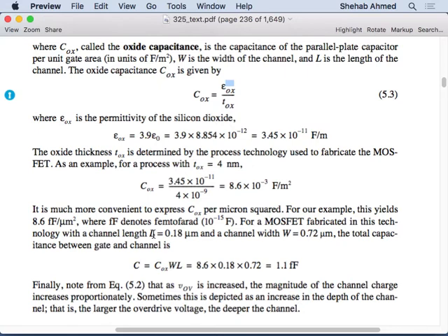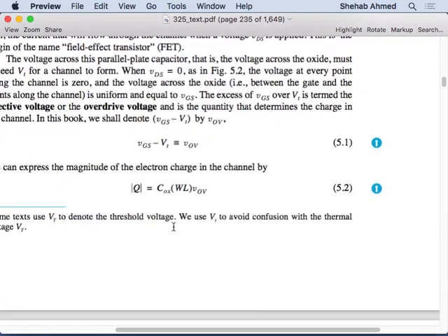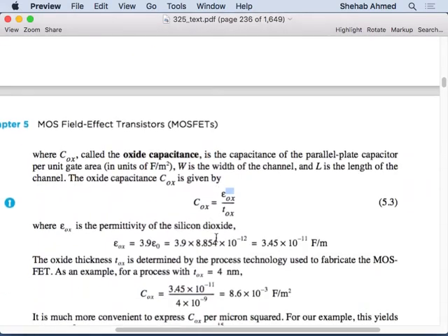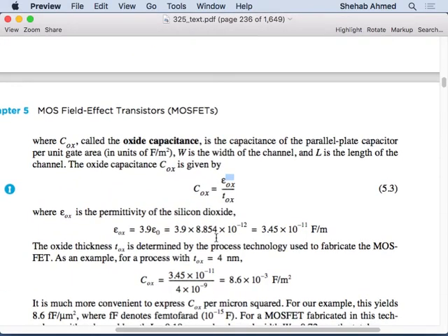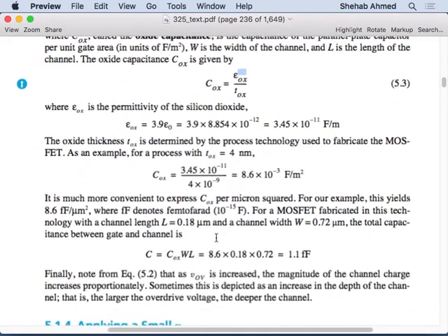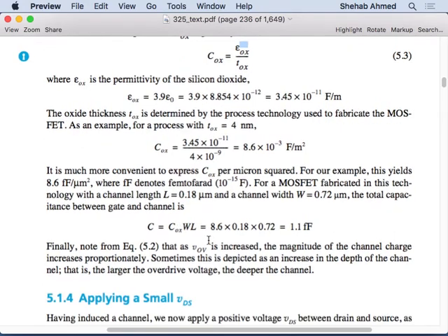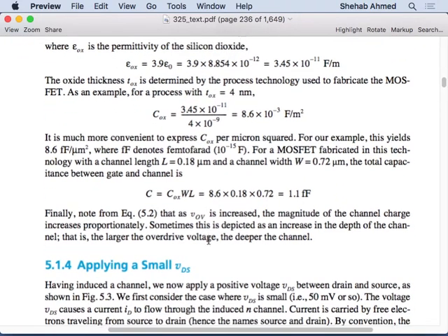So all of this is, we're trying to see how much charge I'm storing, right? All of this is basically this equation, but I'm going to take COX times WL and combine it into a capacitance, which also has a cross-sectional area. That's really what they're saying here, because capacitance depends on the thickness and cross-sectional area. So they've put all of those together, and they're telling us that this is a process-dependent parameter. It makes a lot of sense that it's a process-dependent parameter.